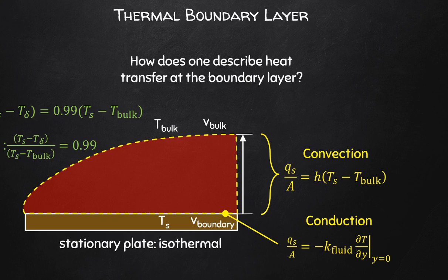Also note that some fluids like water tend to be opaque to radiative heat transfer from the surface of this flat plate. So only conduction close to the surface, and convection through the rest of the fluid, would apply. So with something like water, even if the plate is very hot, there won't be radiation as a mechanism. The major mechanisms are convection and conduction. This is obviously not the case when dealing with fluids that are radiatively transparent, like air, for example.